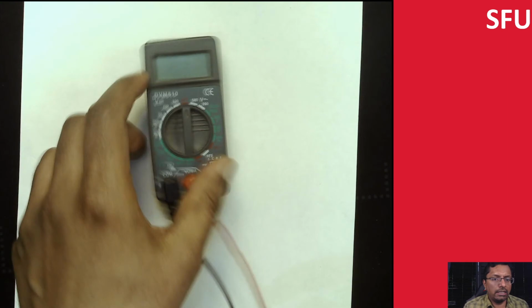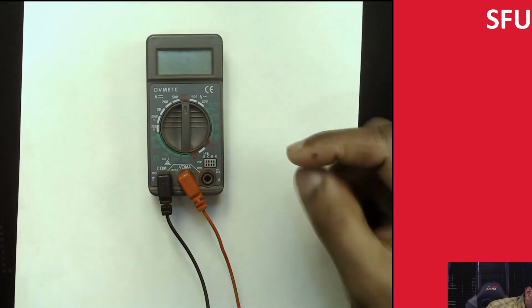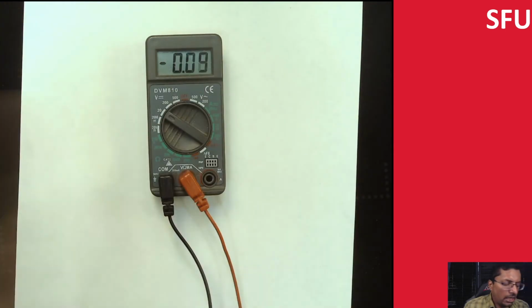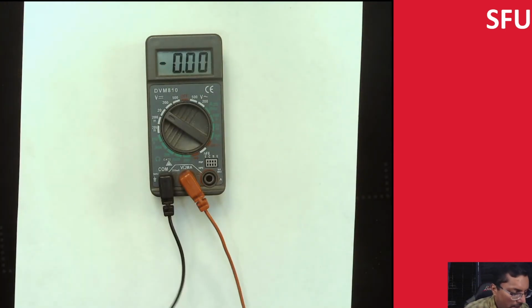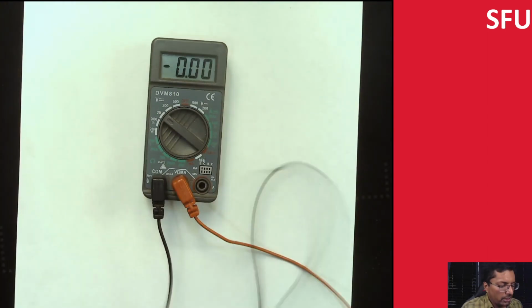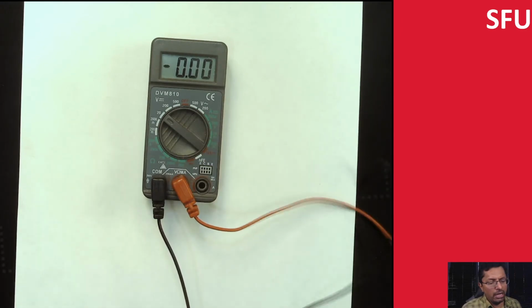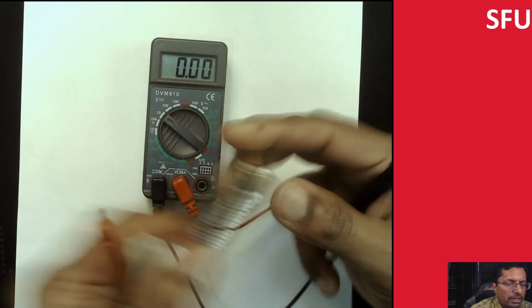What needs to happen is if you want to measure some voltage, we need to use this as the reference voltage. So let's try measuring some voltage over here. I'm going to select a range. I'm going to select from 0 to 20 volts, the 20 volts range. And then I have two batteries over here. This is the AA battery.